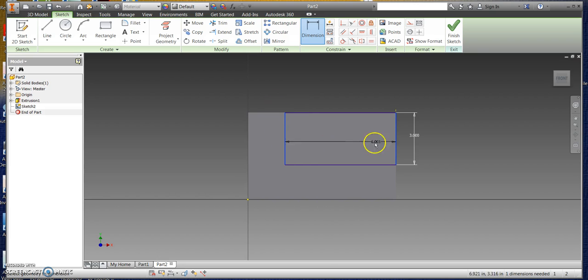So I click on one line and I go over, don't drag, click on the other line. Now I have the number. I'm not dragging right now, I'm just moving it around. And I'm going to move it. I always like to move the dimensions up off the part. So up here somewhere, and I like the 6, in this case, the dimension to actually be between the arrowheads. And wherever I click, it will set that number and give me the option to change it. Oh, in this case, I was real close to 6, but not exactly. And in the CAD world, we need to be exact.